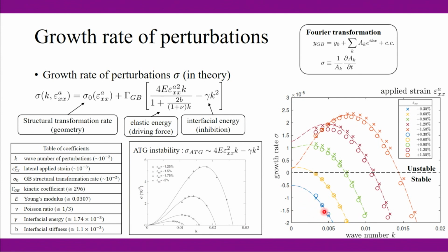So you set up something wavy, and you're going to see the amplitude decay to flat. Nothing happens. And we found that, as I just mentioned, there's a critical threshold for the strain. It's roughly around 0.45 or 0.55. So 0.3 plus or minus doesn't matter. It's going to be less than that. Everything just decays to a planar flat interface.